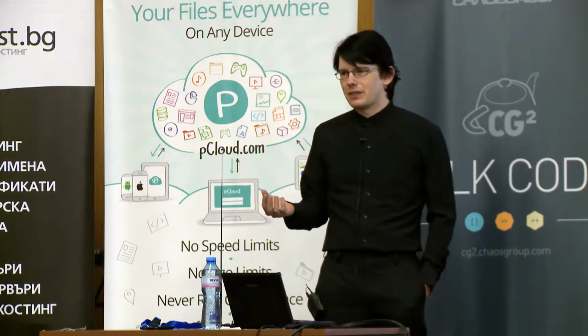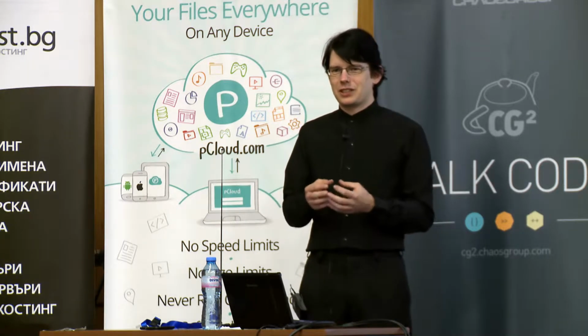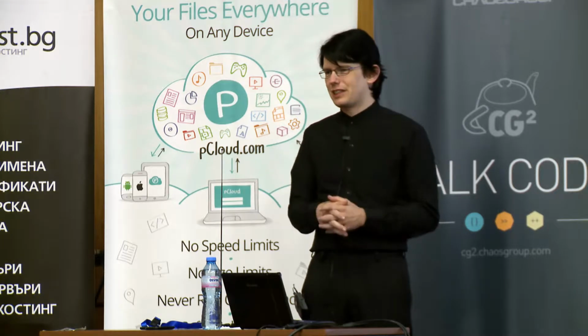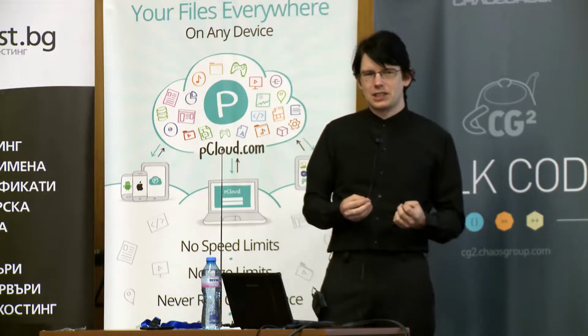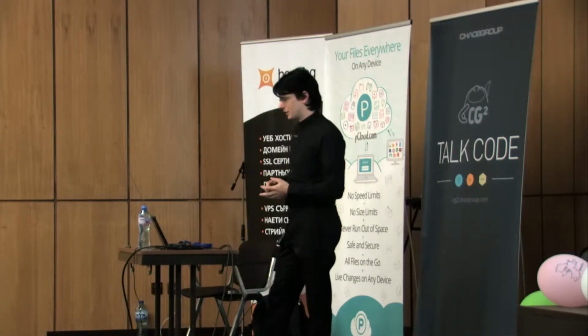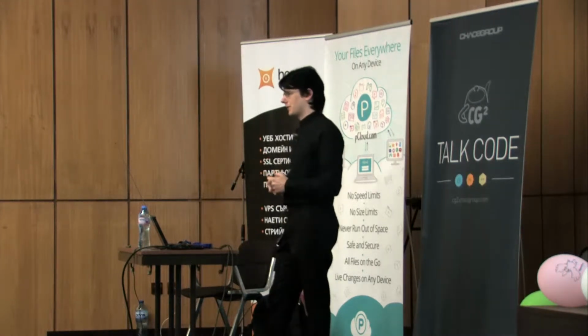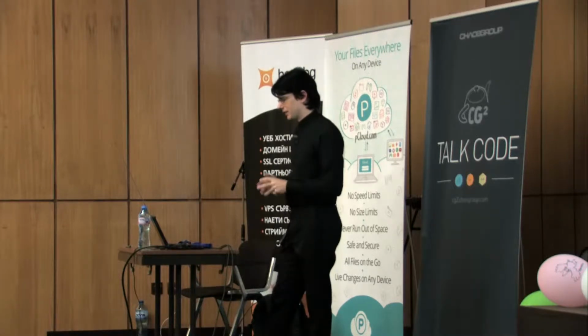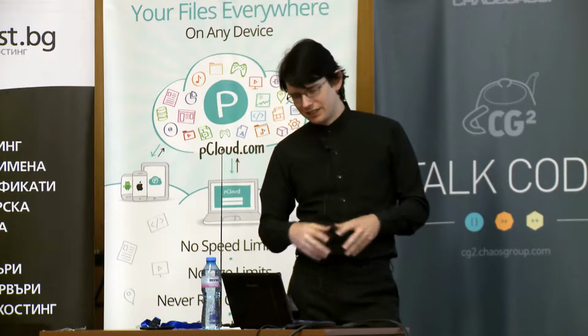doesn't release. So basically, yes, you have this generic radio device, but the manufacturer ships it with a firmware that's specifically for Wi-Fi only or for something like that. And you don't have the information, or often also not the tools to actually do anything else with those devices, because it's in some DSP ROM, or even hardwired logic inside the receivers. So they use SDR technology, but they have removed the flexibility from that. And that's sort of sad.